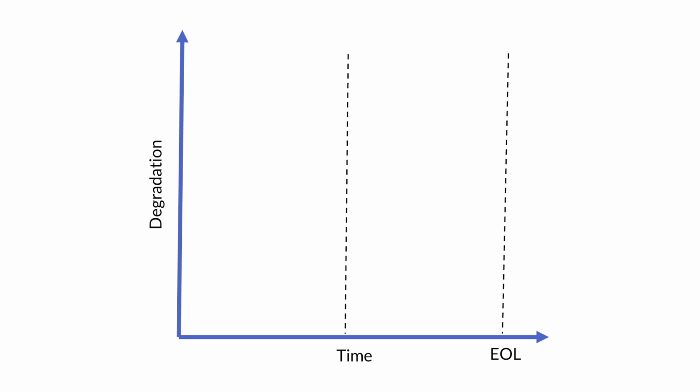What is prognostics' core idea? The idea in the simplest shape is to have a single feature, such as a temperature, and imagine that it's going upward. Then you can extrapolate the trajectory into the future. Once it reaches a given threshold, you know that that's the predicted failure, which can be different from the actual failure point. But essentially this is what we do. We try to extrapolate what's going to happen in the future.